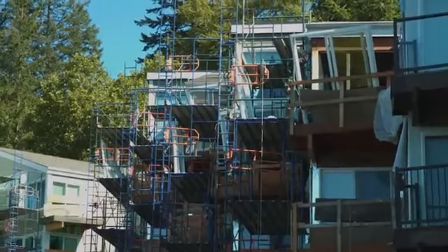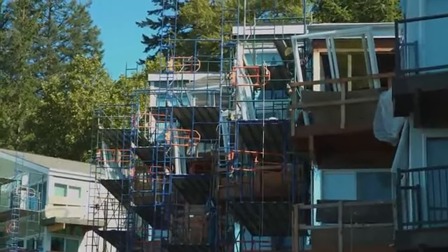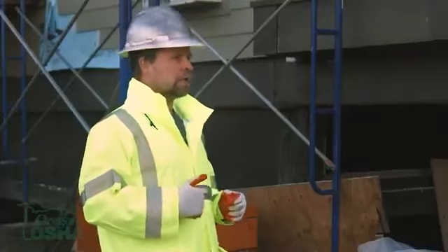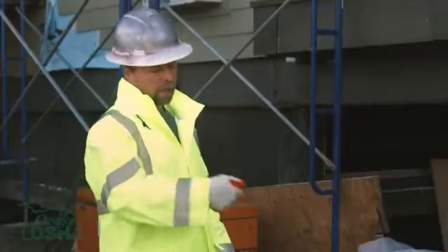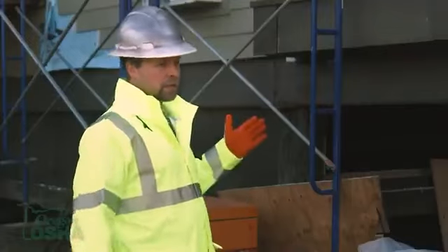At this building, we use anchorage to attach our linear ropes for our harnesses, and it's set up on a roof. Each ridge of the roof has anchorage in there. On this particular building, it was already pre-installed, but we verified it was installed correctly, because you don't want someone to have mistakenly installed it just over plywood, where it will just rip right off. You want to make sure there's solid framing on both sides and the proper fasteners. You don't want to just kind of install it.